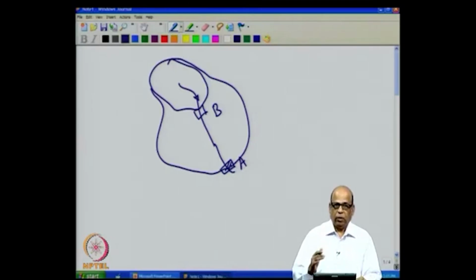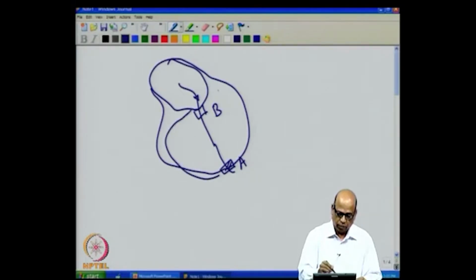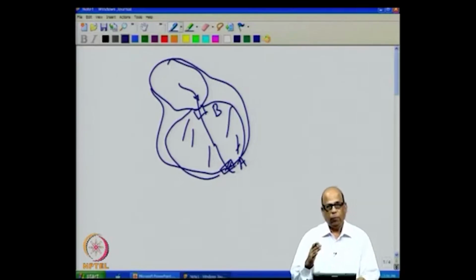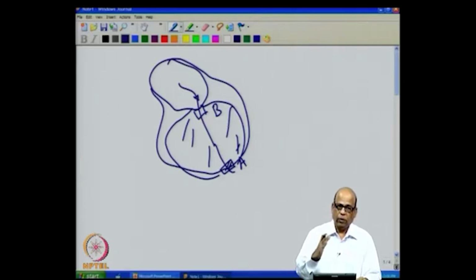So, the flows at A must be greater than or equal to the flows at B, and typically they will be this flow plus all the intermediate catchment flow that has not been recorded at B. If you plot a double mass curve, that is, flows at this location with respect to the total aggregated flows recorded at B, you must expect a straight line, and typically the cumulative flows at A as time progresses will be greater than the cumulative flows at B. So, this is one analysis that we do. I will demonstrate this with a particular case study.